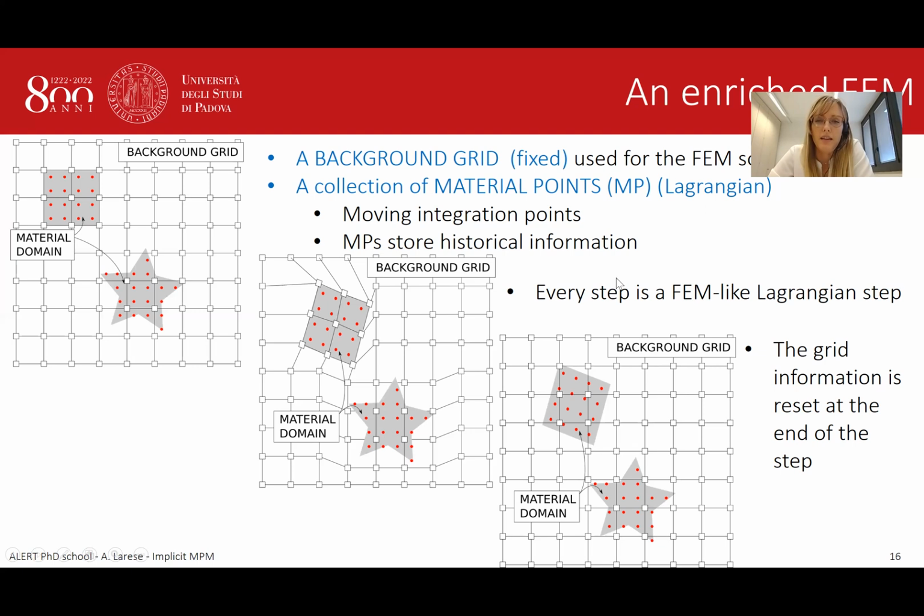So what I was saying is that there is one difference, which is not a minor difference, since it's a mathematical problem. At the beginning of our simulation, we can decide where to put the material points, because it is the code developer who decides where to put the material points at the first step. But then it is the process that makes the material points move, of course the governing equation, but also all the calculation. That means that since these red dots are nothing but the integration points of our finite element grid, at the beginning of the simulation we can decide that the position of these integration points is optimal, that is, on the Gauss points. But after the first step is gone, you cannot decide it anymore. So the position of the integration points in our calculation is arbitrary.